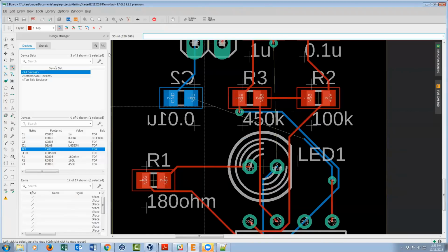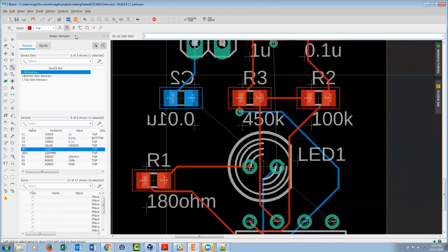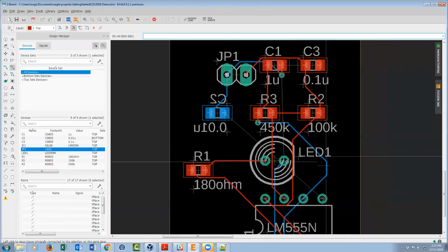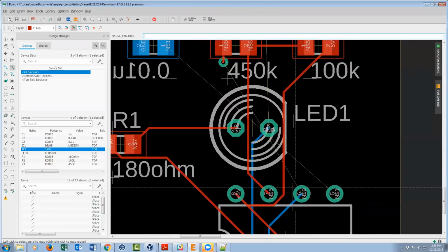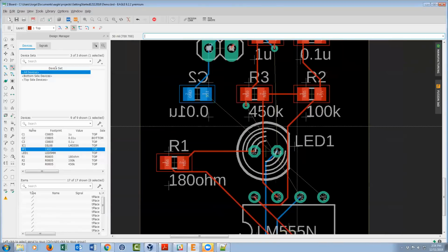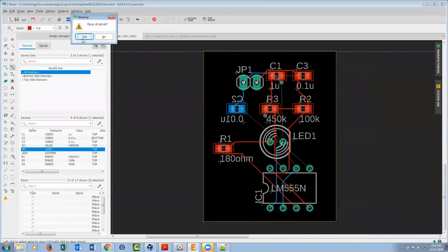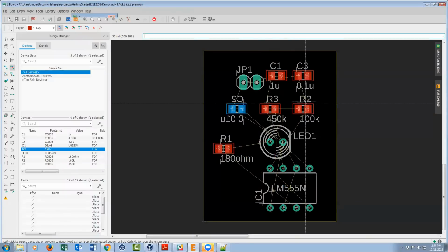The default mode is basically one segment at a time. You can do all connected copper. So here it'll do the whole thing, including any vias that are along the way. You can do connected copper that's on the same layer. So like if I do this one and I click here, it'll leave anything that's on the top. So it'll leave this via and this trace because only the bottom is on the, as you can see right there. And it's stopped here at a pad. It'll always stop at the connecting point. It won't continue past one. And then finally, if you just want to rip everything up, you can click here, clean everything out. Now we're back to all AirWires.